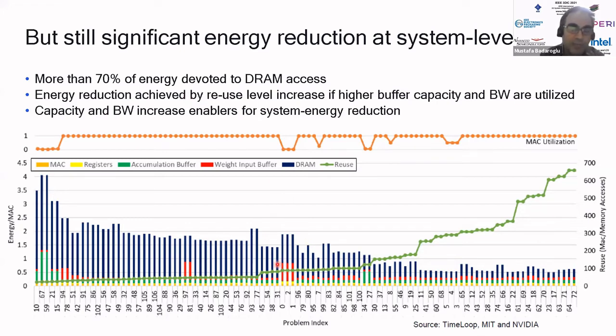And there will be an order of magnitude energy reduction, despite the fact that your tier-to-tier connections are not occurring at a lower capacitance compared to 2D. Because with 3D, you have both a high capacity and high bandwidth improvement that you see at the application. At the end, a significant energy gain is observed because of the cache capacity increase.